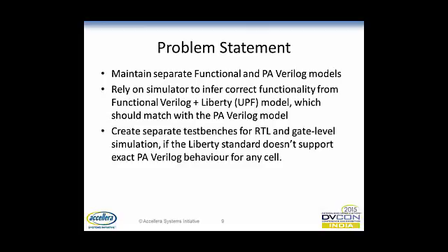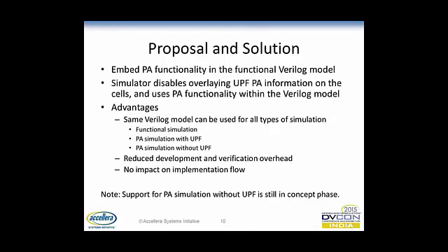If that doesn't happen, then the impact is that they have to maintain separate test benches. One will be running at the RTL and post-synthesis stage where this overlay is happening, and then one separate one for post-PNR where you are just using the power-aware Verilog models. So how to get rid of this?